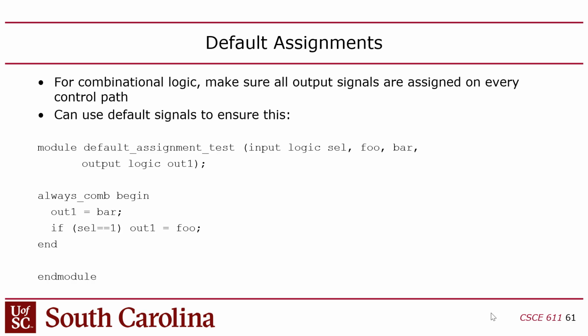So when you create something sequential with some memory, when you synthesize it, does it actually create a flip-flop or a latch or something? Or does it use the memory for it? Well, that's a good question. There are flip-flops on the board, on the chip, and it's going to allocate those. It's going to map one of those and use it. I've never actually tried to make a flip-flop with LUTs. You could create a LUT-based circuit that's cross-coupled and maybe create your own flip-flop. But no, there are hard transistorized flip-flops on there.